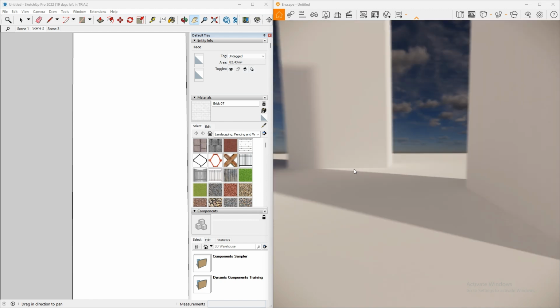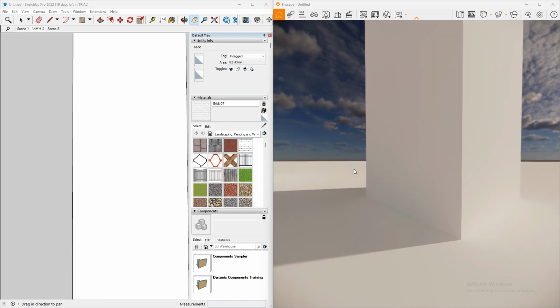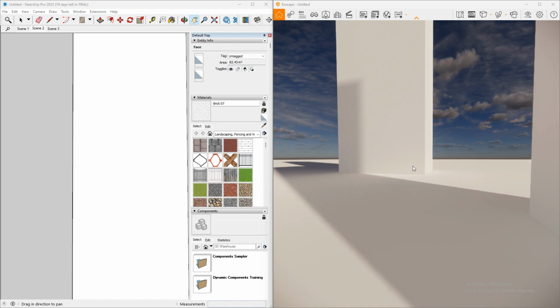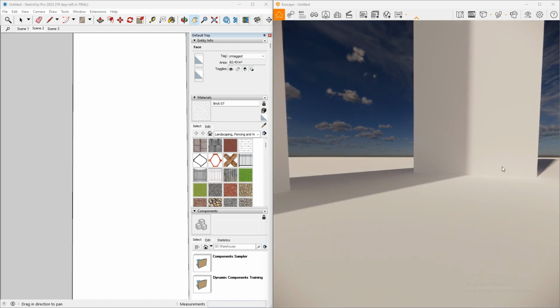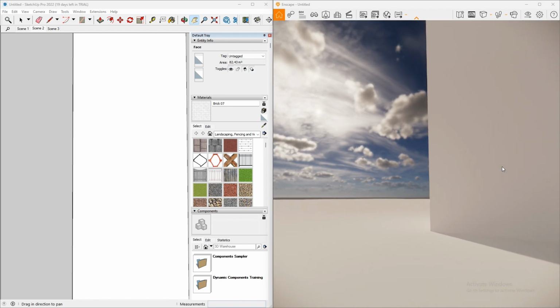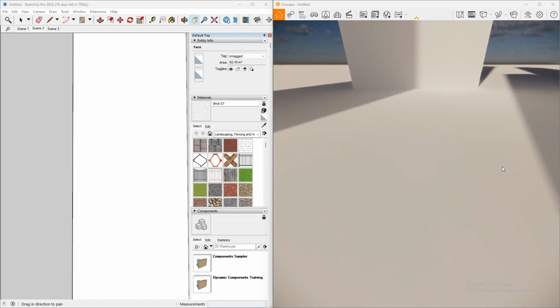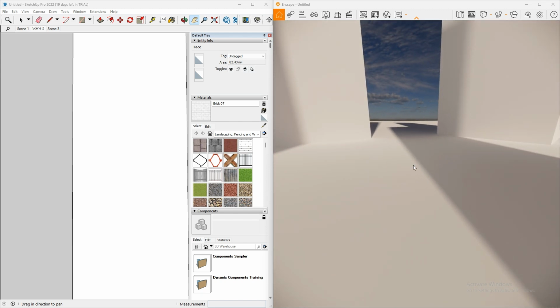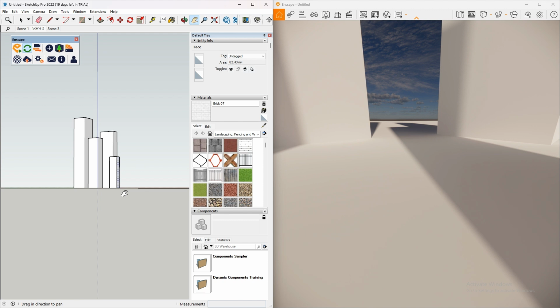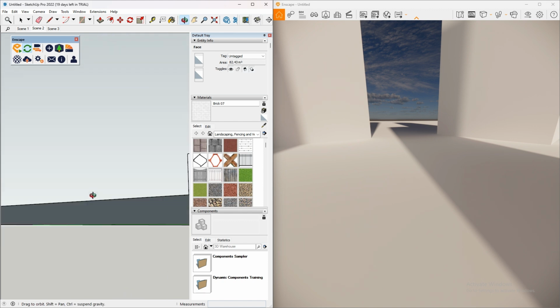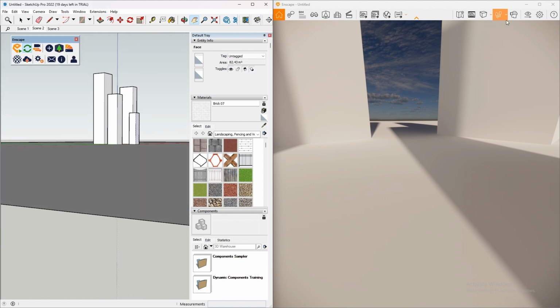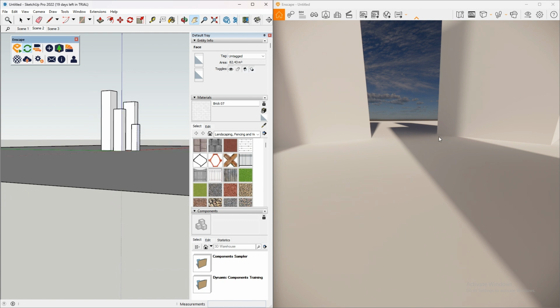And it has the camera located at the average eye level of a human being. Now, the only catch to this is that you must have a floor to your model, even if it's just a 2D plane, such as this. Because without that floor, if you click on walking mode, and before you saw how I dropped, it will just go straight through and just keep falling until it eventually stops somewhere in the abyss over here.